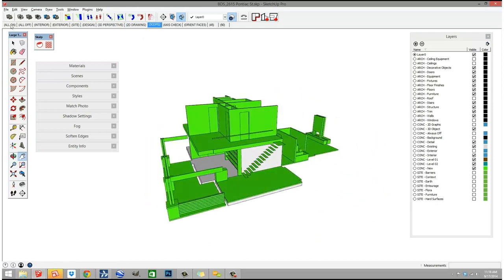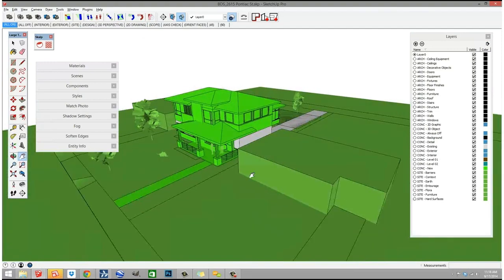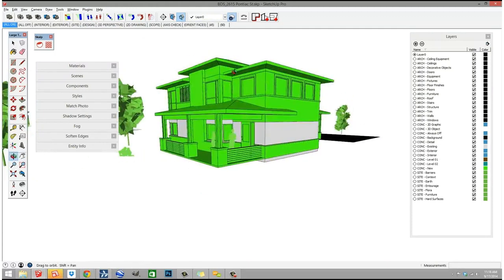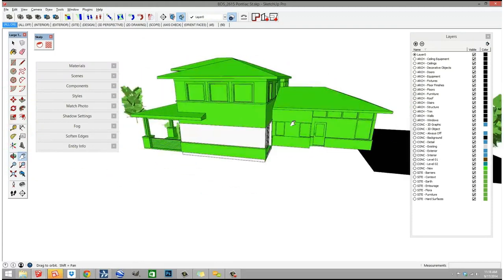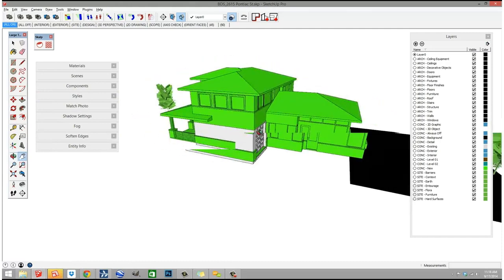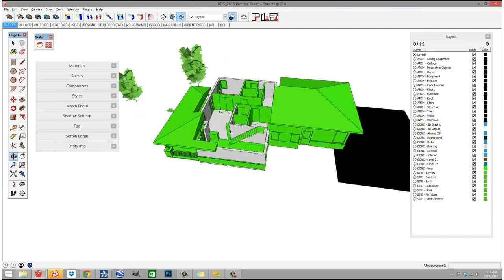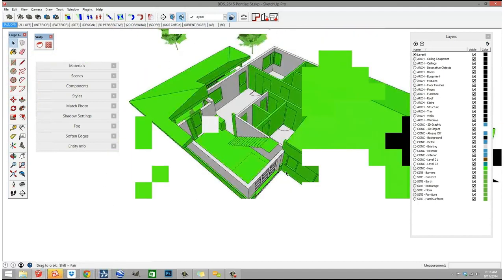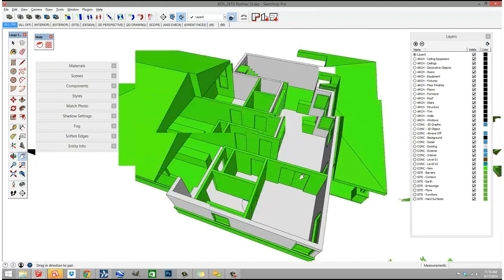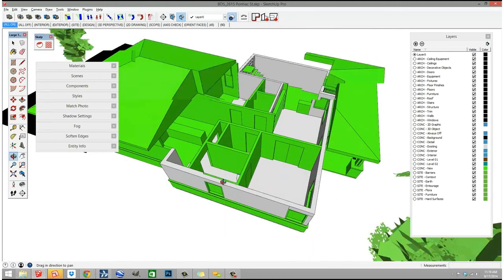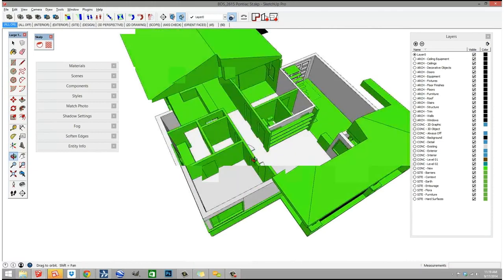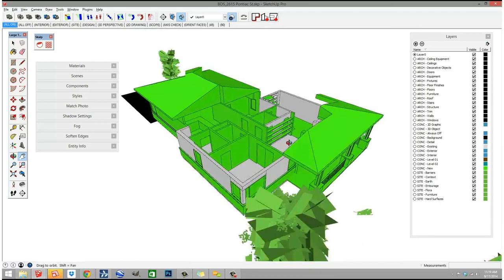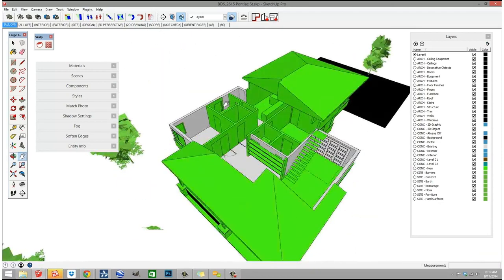Now what you're seeing here, if I go back to all on, and let's just get rid of our site here for a moment, you can see that when you're on the scope diagram, this is a color by layer style. And so what that means is that if I were to hide these, I can see the existing walls and the existing doors, and I can see my new wall. So this project evolved in such a way that we pretty much blew out the entire house, but you can really start to see that if you were picking apart a rather large existing building, this is a pretty valuable diagram to have to really understand where you're at in the model.